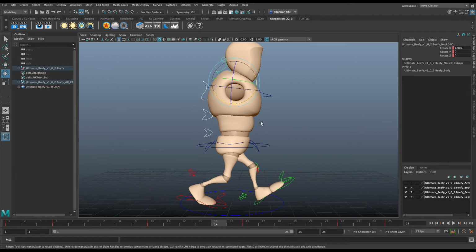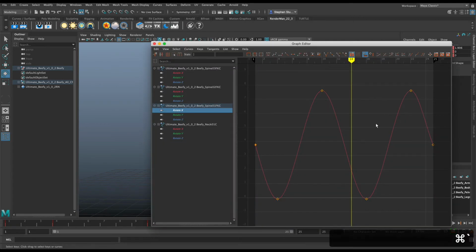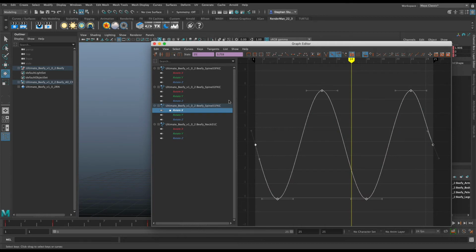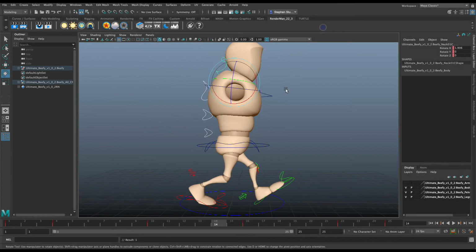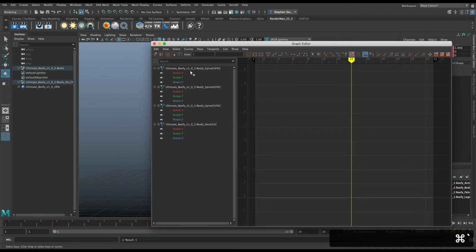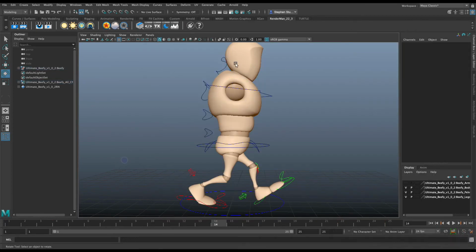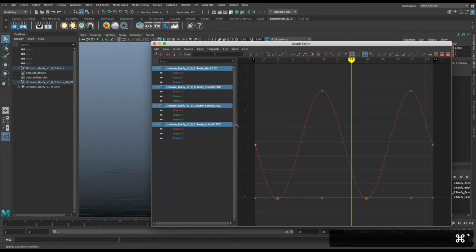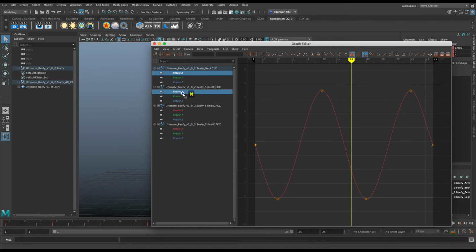Now, I probably want to bring that back down, and one way that I can do that is because this is sort of moving back and forth, if I like the back motion, then I could just grab all this, and I'm going to deselect that rotation, so that I'm dealing with everything. Actually, I'm going to deselect, select them all again, press Q on the keyboard so I don't accidentally rotate it. And I'm going to go back. And then I'm just going to select the rotate axis.